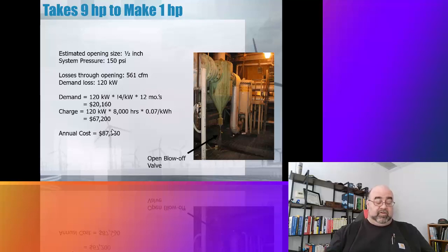Things we found as opportunities: increase the capacity of the receiver. Compressed air receivers are extra tanks elsewhere that could be brought up to pressure to allow the compressors to unload, basically cycle. Balance the load on both compressors. They did have an unbalanced load. Install surge tanks near the bag houses that were served by the compressed system. This reduces the load on the compressors while improving the system line pressure, etc.